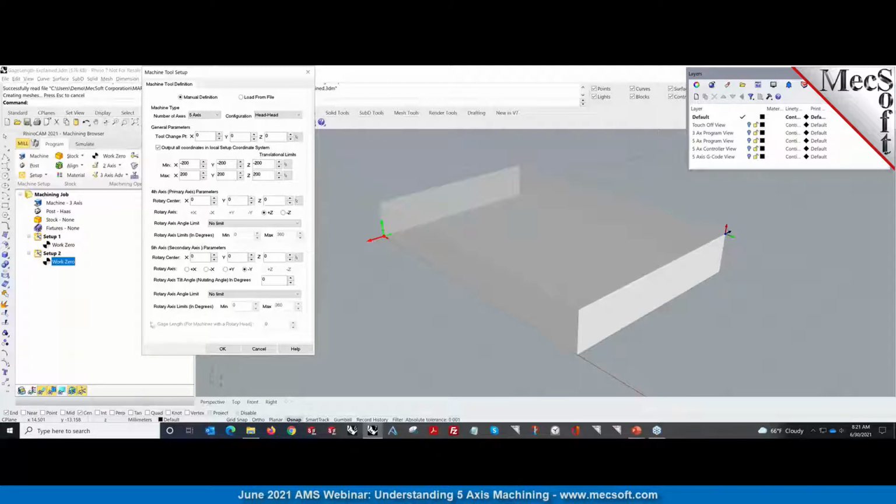One important thing that we need to specify is also the axis limit. Some of your machine tools might have axis limits because they cannot turn more than 360 degrees, for instance. Some of them running on rack and pinion systems could have no limit. But you can define the limits of your machine tool here by specifying this. I'll say 0 to 360 in this particular case.